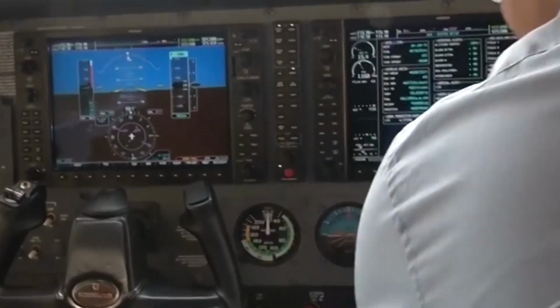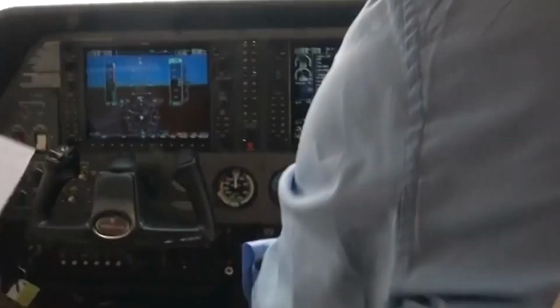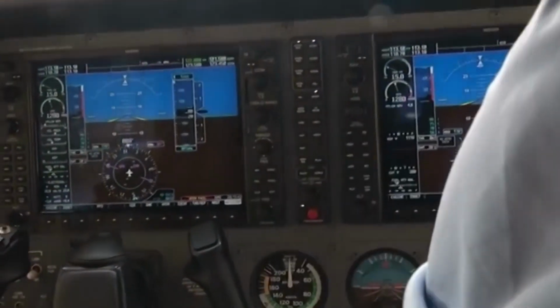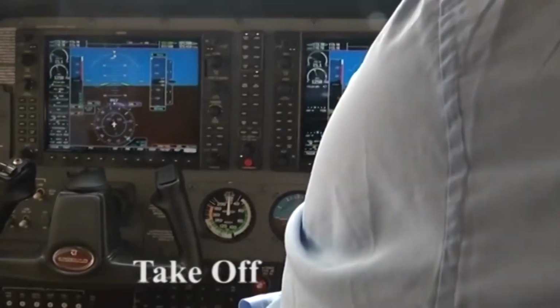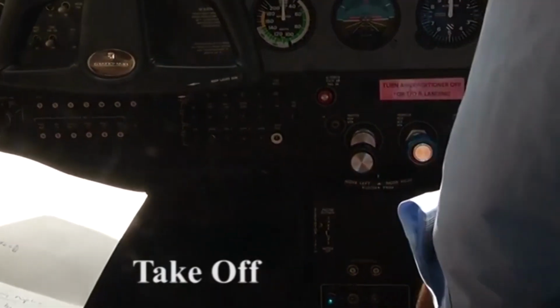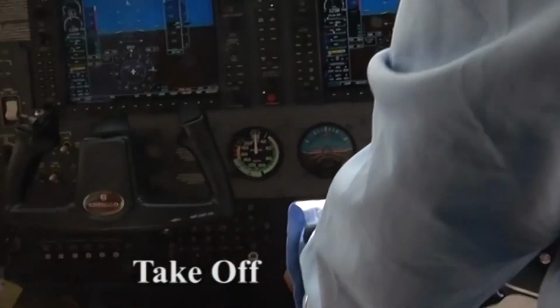All controls are checked for free and correct movement. Cowl flaps are open. Flaps are being set at 10 degree position for takeoff. Flaps set for 10 degrees, trimmer set for takeoff, rudder trimmer set for takeoff. Elevator trim and rudder trim are being set for takeoff. Fuel on board. Fuel selector is on both. Fuel is being taken from both the tanks.